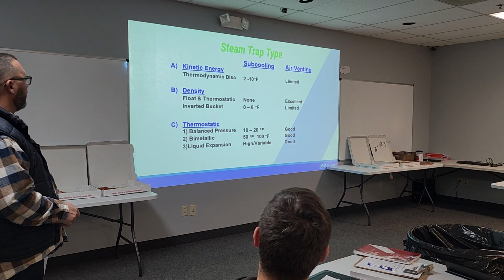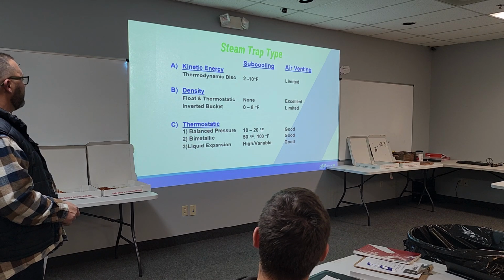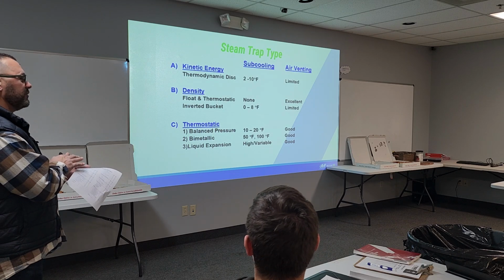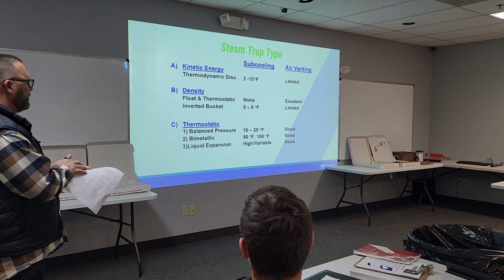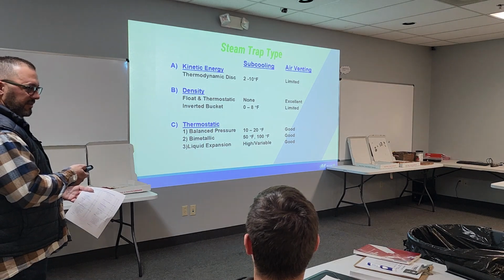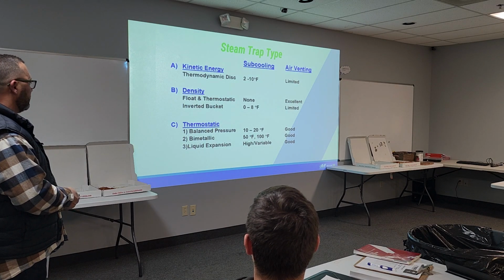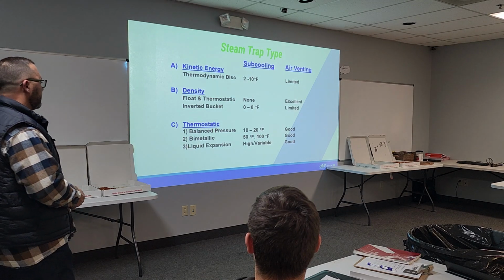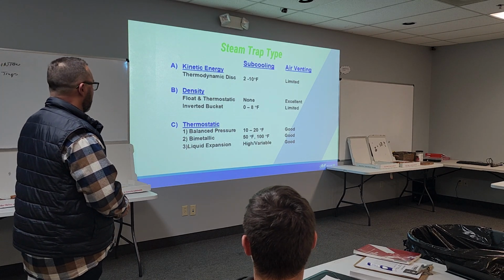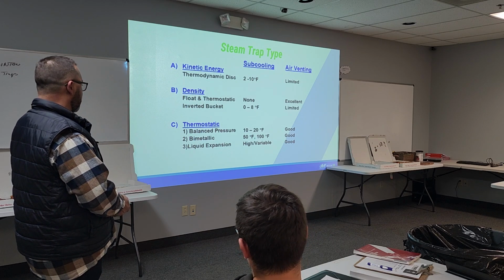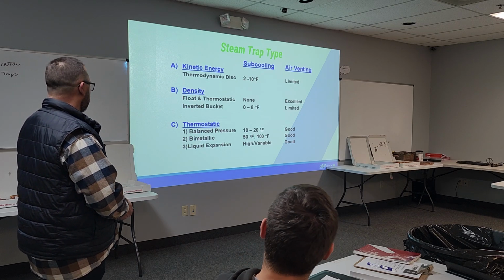And look at that. Look at the subcooling, and even worse, the bimetallic. So the bimetallic's just 2 dissimilar metals, and as it heats up, they separate, and that's what seals off the head and seat of the trap. And look at that. I mean, that's an air vent. That's not anything I've ever even sold. I'm sure they have their applications and their spots, but I certainly don't.